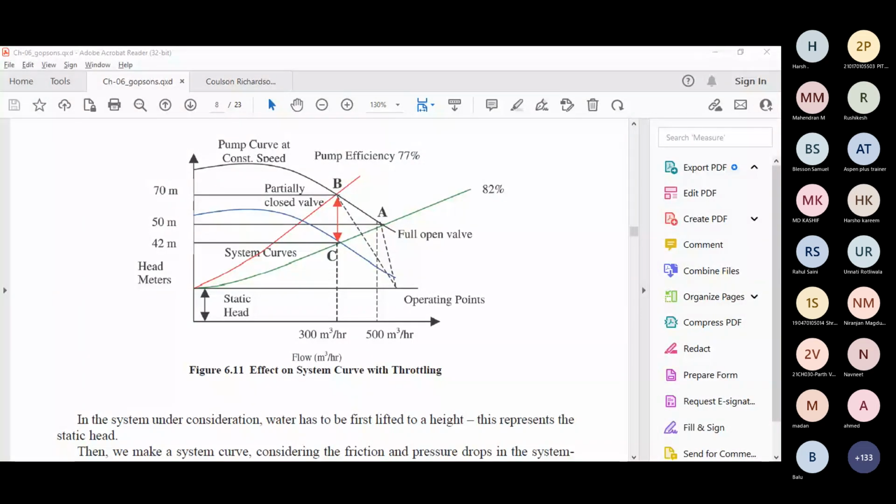But mostly, as a standard, 20 to 25% of the desired flow rate is given in the circulation line, because we never want our pump to run in a total shut off. Recirculation line: if I am given a task to always operate at BEP, then I can divert any amount of flow rate. Suppose my pump went into complete shut off, 100 meter cube is the design flow rate, so all my 100 meter cube will go through the recirculation line. Generally, as a thumb rule we say 20 to 25% should be diverted in the circulation line.